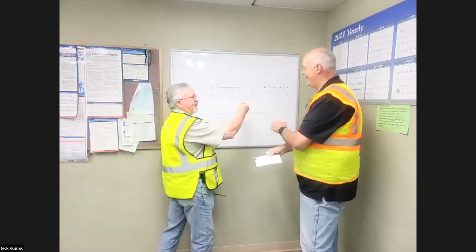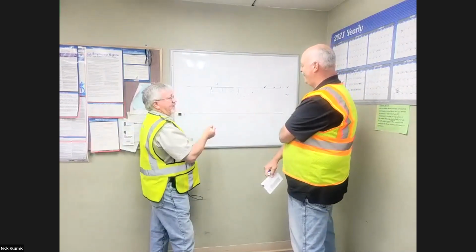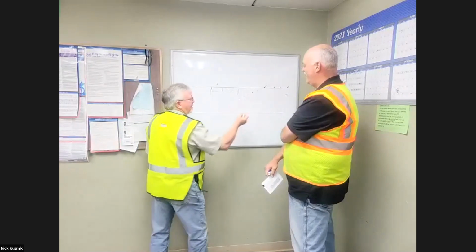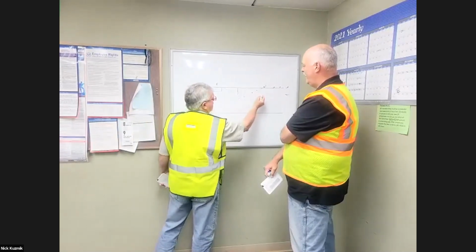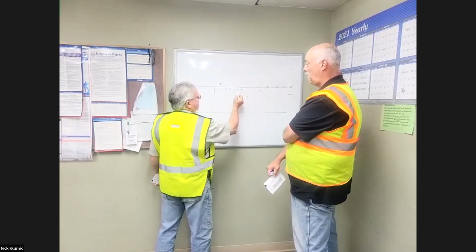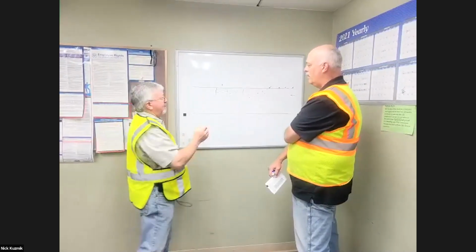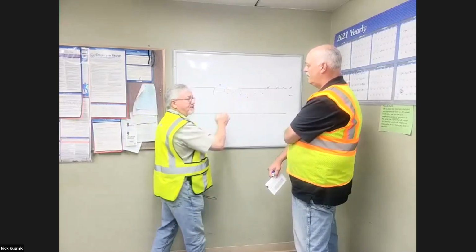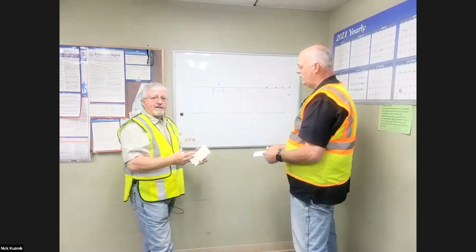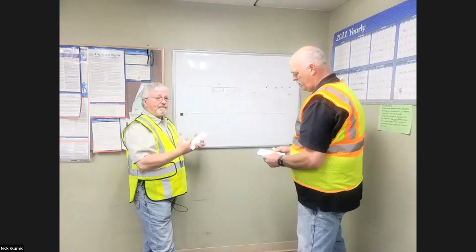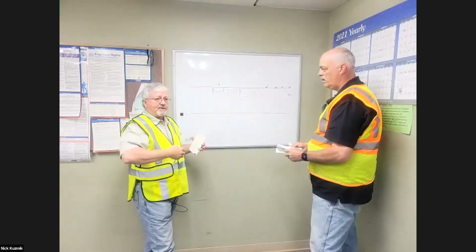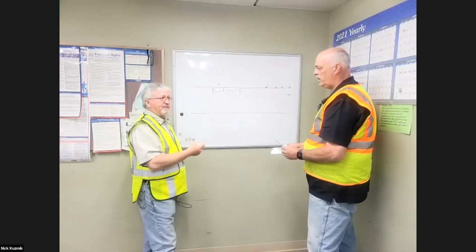They miss your 3 signs, then they miss your flagger, then once they hit these cones, this buffer zone gives them adequate time to slow down and stop. The buffer zone is set up based on how fast the traffic is going, and how quickly you're going to be able to stop.